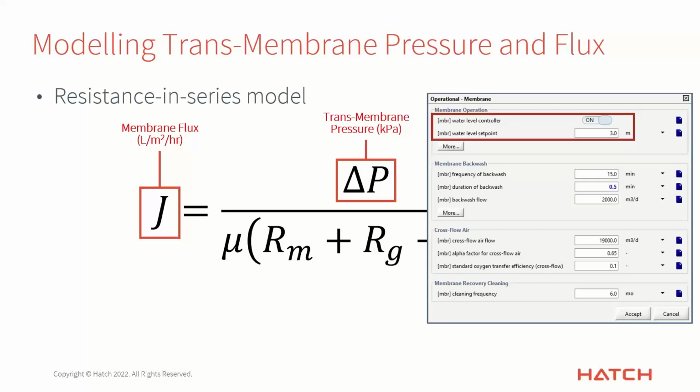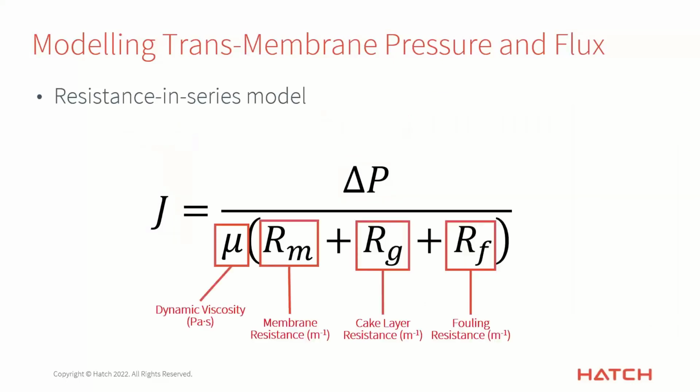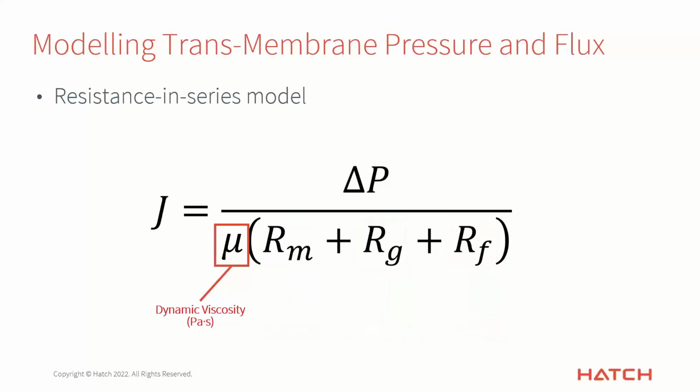It essentially keeps the system such that the water level is constant. And that's a fairly realistic way to do it. In one of the previous versions of this, very early drafts of this model, we had the controller on the transmembrane pressure itself, but we learned that it's much more realistic to do it on the permeate pump. So we know those two values, we can calculate those, and then we have these other terms. So we can calculate the TMP once we know all of these things.